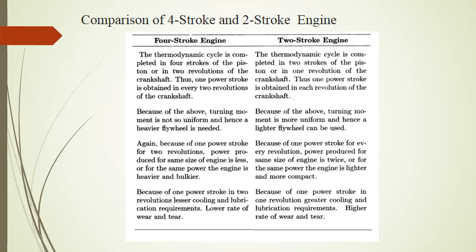And if we want to make both the engines of the same power, that is two-stroke and four-stroke engine, then definitely we will have to compensate the factor of 2. To compensate for the factor of 2, definitely we will have to increase either of the parameters, that is either Pm or L or A or capital N, that is speed.